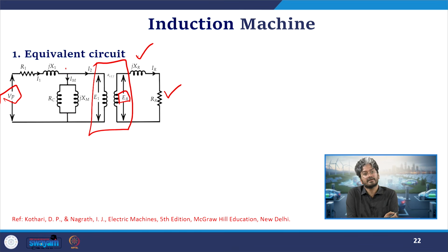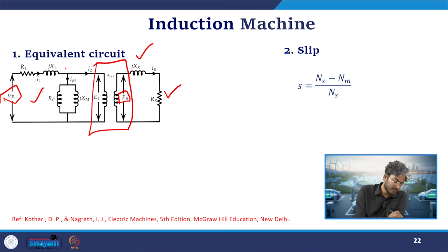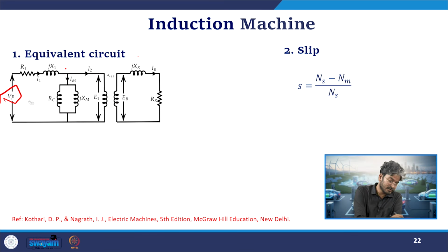the stator side circuit. So when I say power, it means the frequency of induction. Okay, so here it brings us to the concept of slip. The frequency of the stator will be 50 hertz for our conventional supply, whereas the rotor will have a much lower frequency. Because of that, we are neglecting the core loss component on the rotor side of the circuit. They will be negligible compared to the stator core loss. So that's why we are not considering them. Now this brings us to the concept of slip.